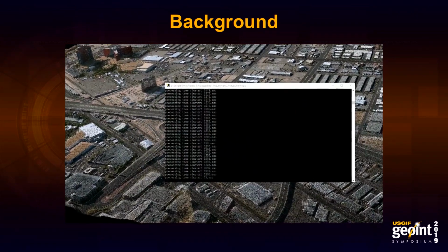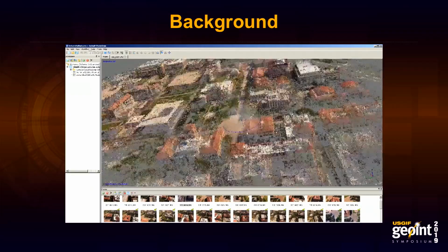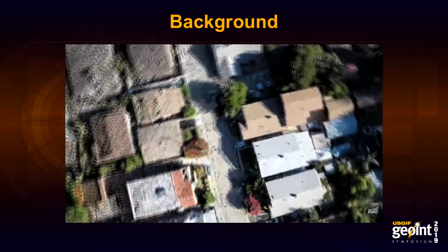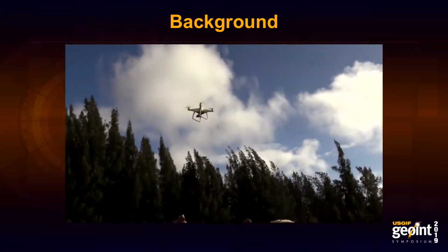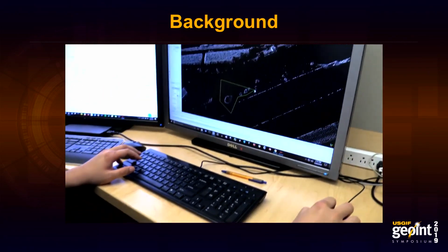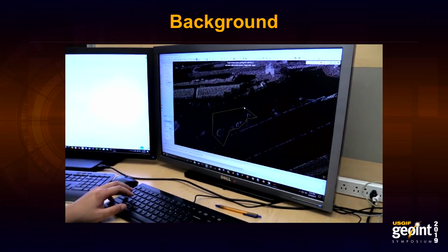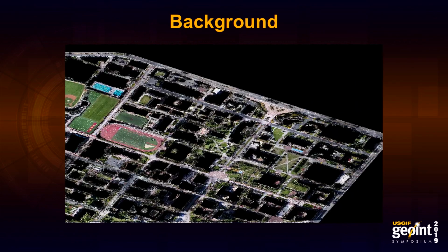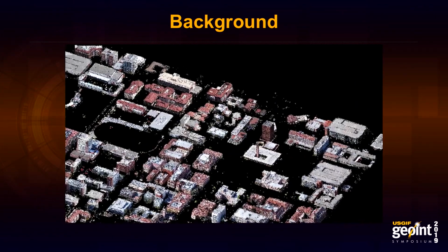Classification and segmentation is currently a mix of supervised and unsupervised machine learning algorithms. It starts with the data, in this case, a point cloud generated with photogrammetry software from a drone collection. The user manually segments a few buildings and trees as training data for the machine to learn how, and then the segmentation algorithms extract ground, vegetation, and building features.